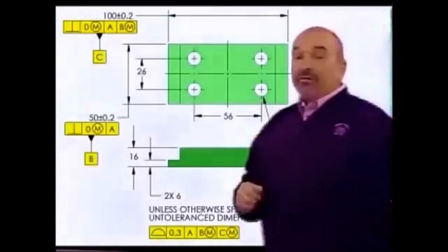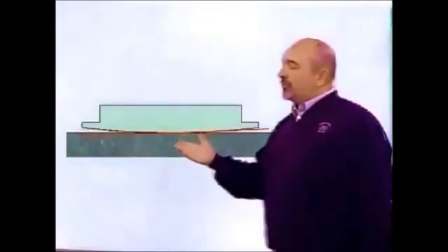If the surface is convex and I place it down on the surface plate to inspect the part, it might rock around a bit. This is showing you that there are several different datum planes that I could possibly use. In fact, if I set it down and it does rock, there's an infinite number of planes. So which one do I use?